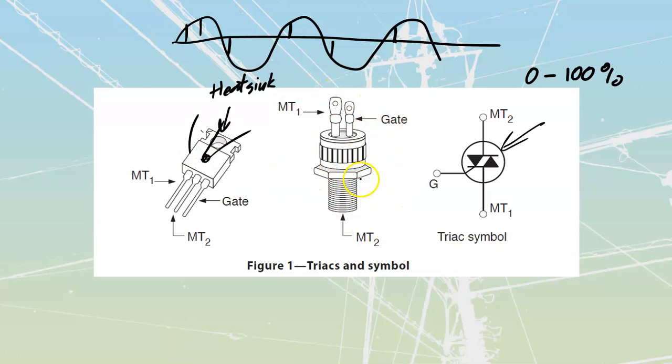We're going to thread it in. Once again, note that this thing actually threads into the heatsink, which means the heatsink is live. Whenever you remove covers from electronic equipment, make the assumption that any heatsink that is inside the box is live. Very well could be. Might not be, but it very well could be. If it's on the outside of the box, guaranteed they have to have that thing attached to ground. But if it's inside of the box, it might be connected to something like this.